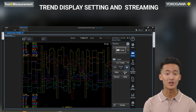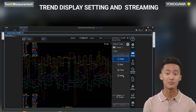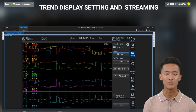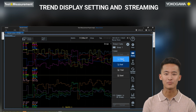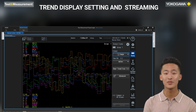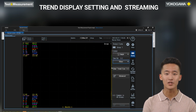Now let's go to Form and click on it, which will open up Format, Times per Division, Clear Trend Execute and Advanced. Click on Form drop-down under which we can see Single, Dual, Triad and Quad forms of displays available, from which we can select appropriate form for measurement. Times per division is where we can select the recording time of trend graph. In WT5000 we can record as low as 3 seconds to as high as 1 day trend graph directly in instrument. For this test measurement, let's configure times per division to 30 seconds.